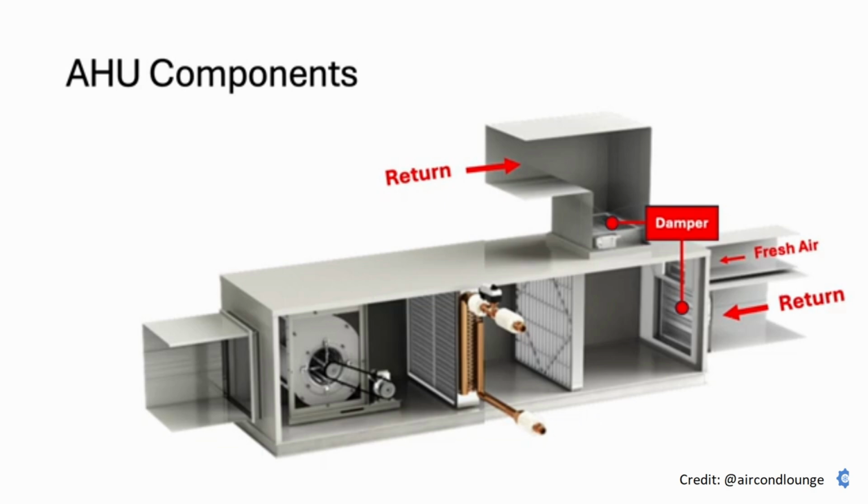Airflow mixing occurs when two or more air streams combine. When we are opening a window, it provides outdoor air mixing with the existing indoor air. In air handling units with air recirculation, the mixing occurs in the mixing chambers. Mixing allows us to balance air quality and energy efficiency. Fresh air reduces contaminants and increases oxygen levels, while recirculated air helps to conserve energy by reusing conditioned air. It is widely used in premises in which heating or cooling is provided by ventilation.